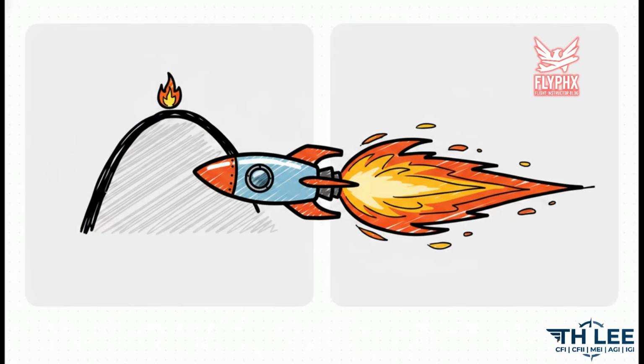Now, finding best power is practically a science. If you just keep leaning the mixture, the temperature hits a peak, and then surprisingly, it actually starts to drop because there just isn't enough fuel left to burn efficiently. That top point, that's your peak EGT, which basically means 100% of your fuel is being consumed.